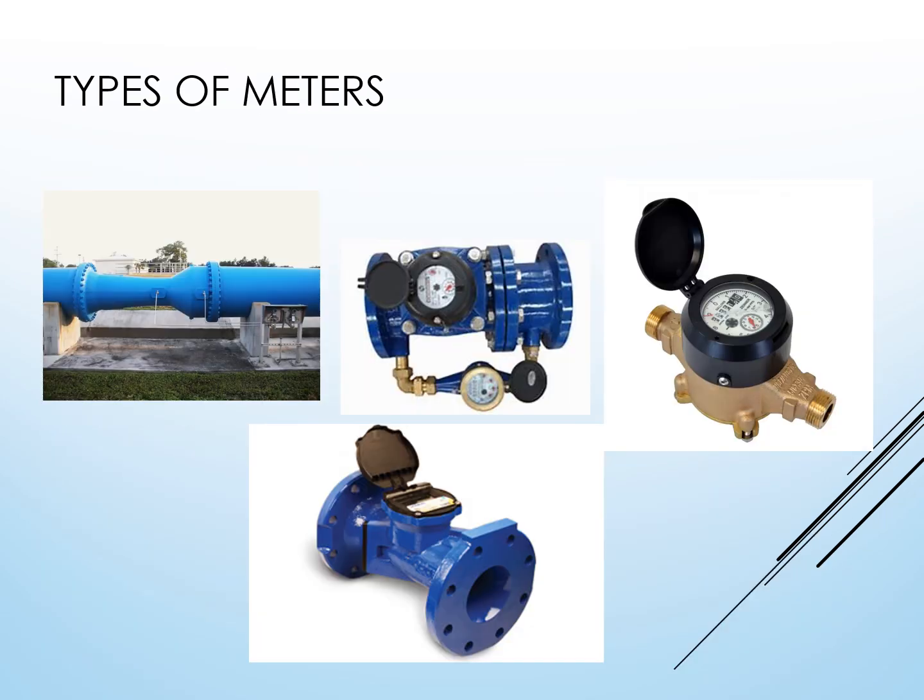We've got different types of meters. You've got Venturi meters, compound meters, positive displacement meters, ultrasonic meters. It just depends on what the application is, and if you're trying to measure large flows or small flows. Whatever the end user is using that water for will dictate what type of meter is likely to be installed.